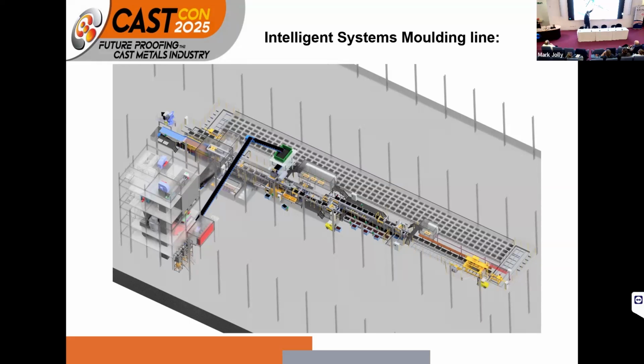So this means when we detect here with the vision control system that there is a broken mold inside, then we mark it as a scrap mold. This means the operators here in the system or core robots or whatever is there will place no filter. We are placing no cores. We are closing the mold, okay, but then the pouring machine, the auto pour or the pouring furnace will know not to pour that.